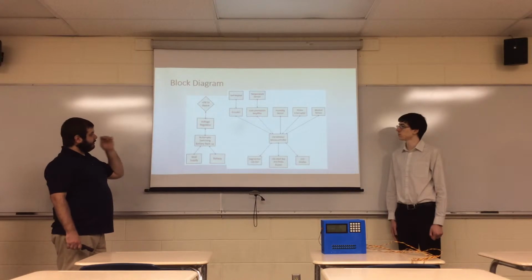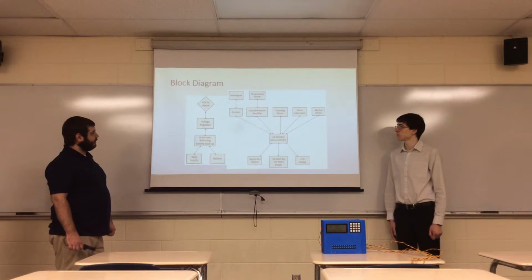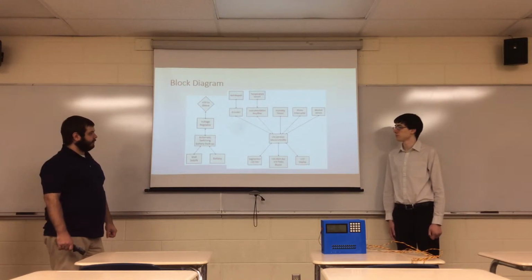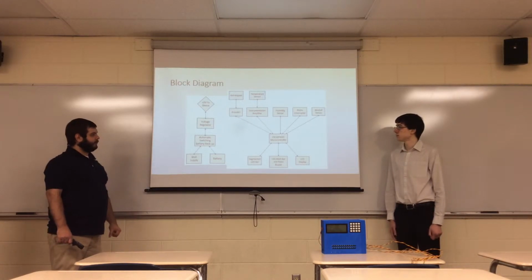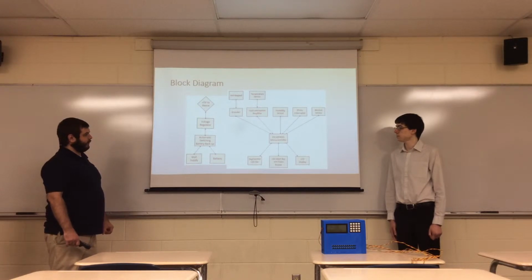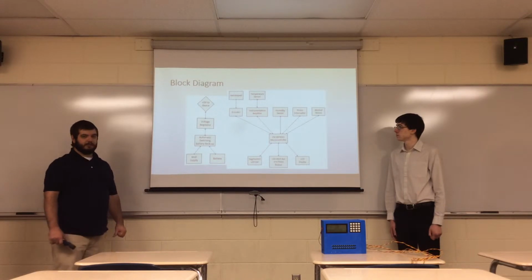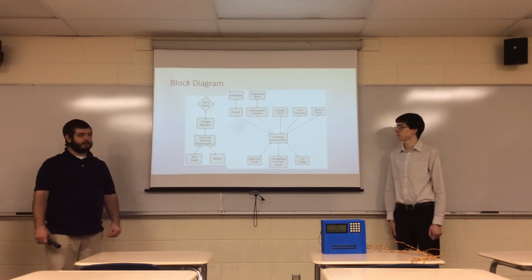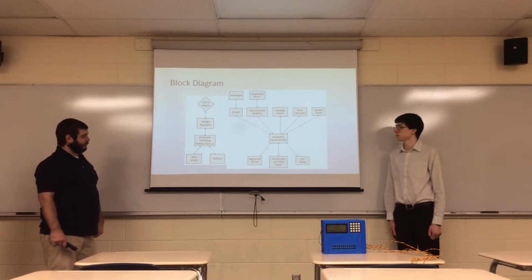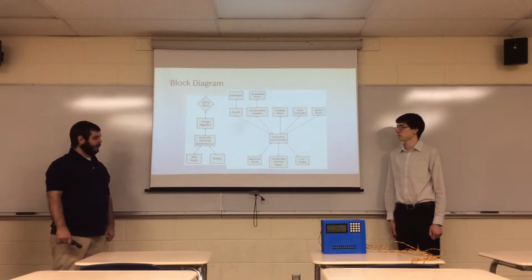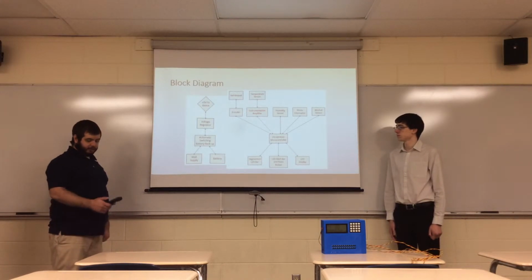Our inputs for our device are a keypad, a temperature sensor, and other sensors. The keypad goes through an encoder to save pins on the PIC. The temperature sensor uses an instrumentation amp to get better resolution, while the humidity sensor and alcohol sensor use other analog inputs, and the photo interrupter is digital, either something's in the way or something's not. The outputs of the device are a segmented LED bar, LED alert bar and buzzer, and an LCD display for displaying the user interface.